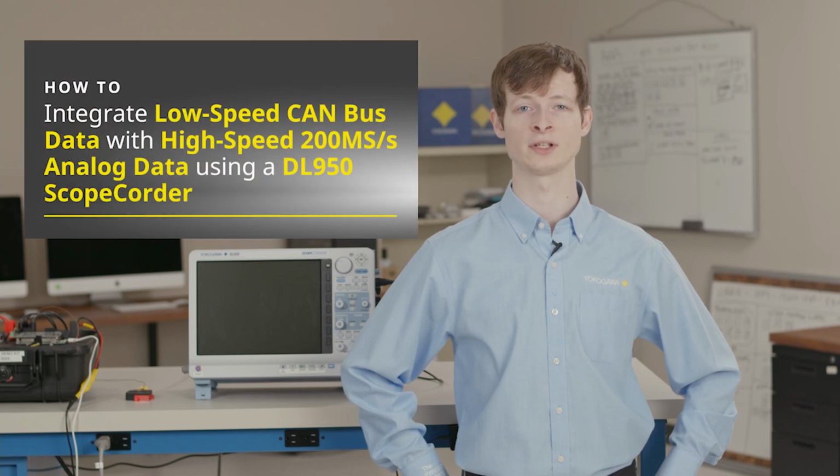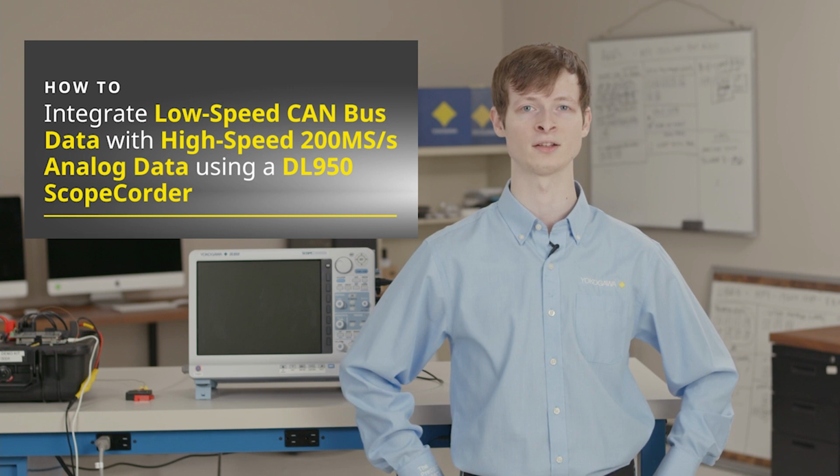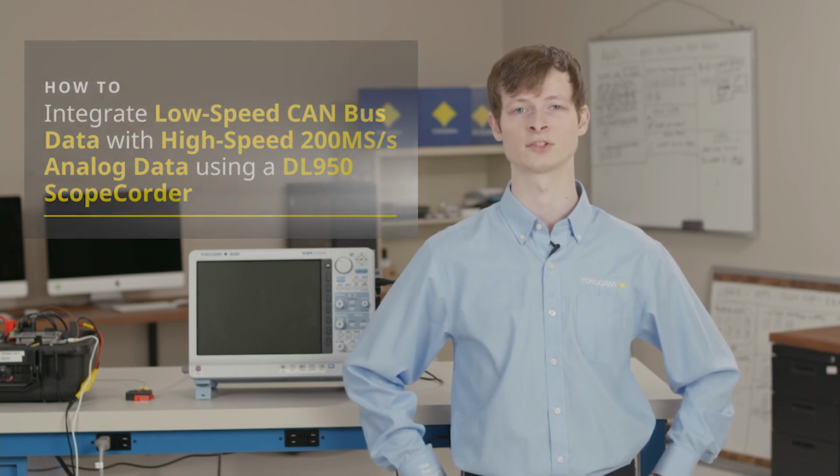Today, I'll be showing how to integrate low-speed CAN bus data with high-speed 200 megasample per second analog data using our DL950 ScopeCorder. For our example, we're going to expand the capabilities of our data acquisition system using a CAN-based wireless thermocouple amplifier from Texense. I will demonstrate high-speed capture of a 20 kHz motor inverter while monitoring the low-speed output of Texense's wireless temperature sensor. I'll also be using an industry-standard DBC file for integration with our ScopeCorder using our symbol editor software.